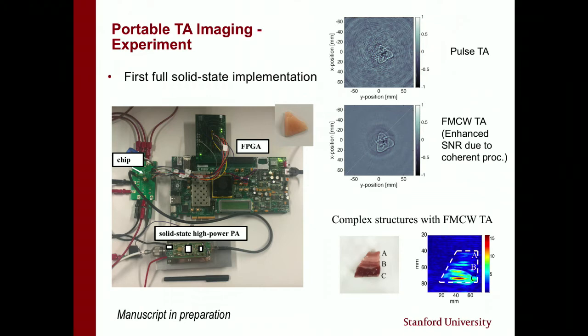If you look at our entire system, because of this integration and coherent processing, we've been able to get it into a form factor that is more manageable. We obviously haven't yet integrated on single chips or small systems. We have an FPGA that does all the data capture, all the processing, and waveform generation. We have our chip that generates the modulation, the output power, the whole signal chain. And then we have a high-power solid-state amplifier that delivers the output power to the tissue. So these three components are all solid state. And for the first time, we're doing thermoacoustics in full solid state without any vacuum sources.